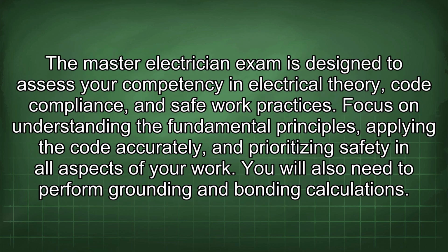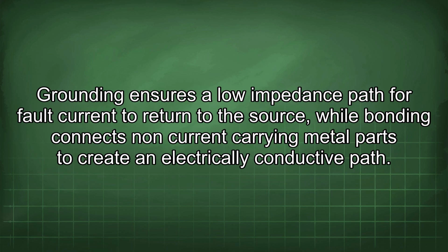The Master Electrician exam is designed to assess your competency in electrical theory, code compliance, and safe work practices. Focus on understanding the fundamental principles, applying the code accurately, and prioritizing safety in all aspects of your work. You will also need to perform grounding and bonding calculations. Grounding ensures a low impedance path for fault current to return to the source, while bonding connects non-current carrying metal parts to create an electrically conductive path.